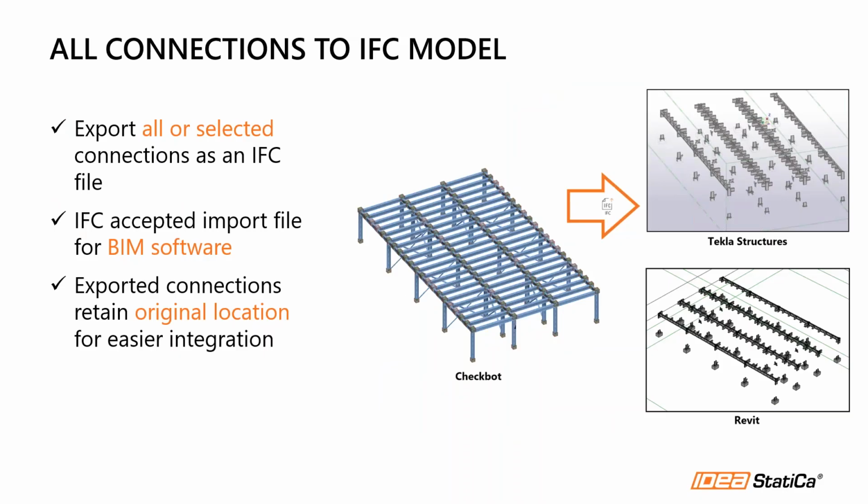Finally, in the video, we show how to create an IFC file from Checkbot. In the video, we selected all the connections and clicked on creating one single file with all the selected connections. Later, the IFC file can be imported as a reference model into BIM applications like Tekla or Revit. However, IFC is an open file format that can be opened in multiple applications.